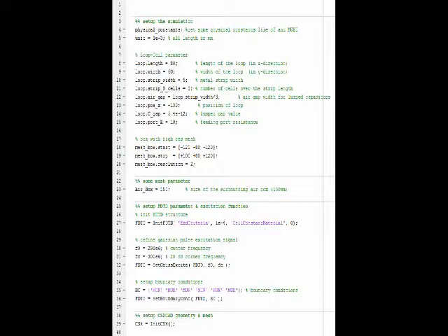The position for the x is negative 130 for the loop, and then we have the lumped gap value as 1.4 times 10 to the negative 12. The feeding port resistance is 10, and we will use this parameter later.